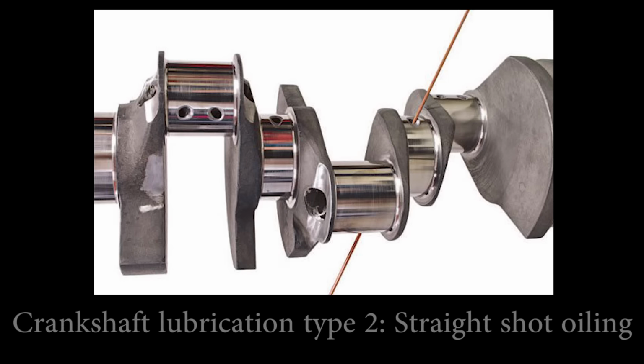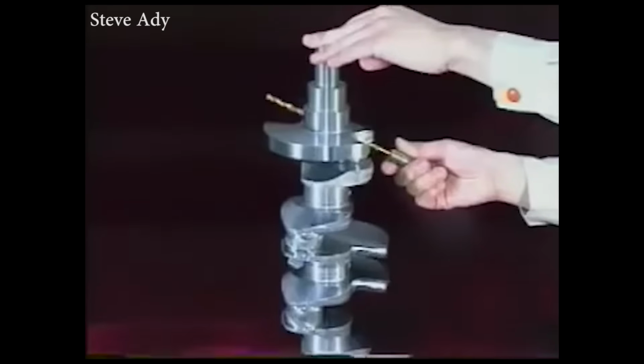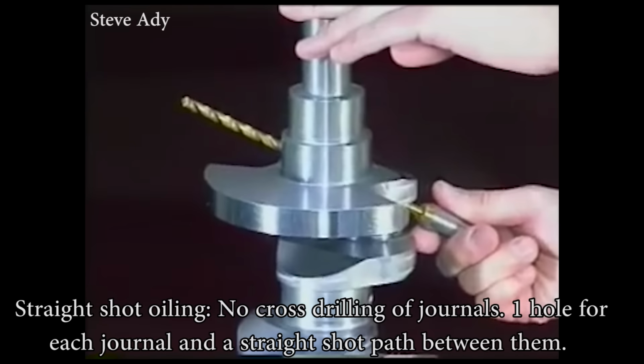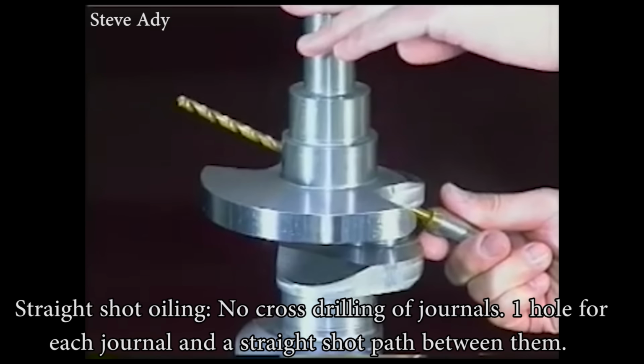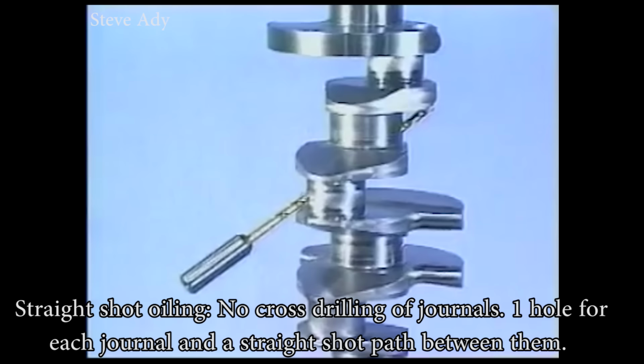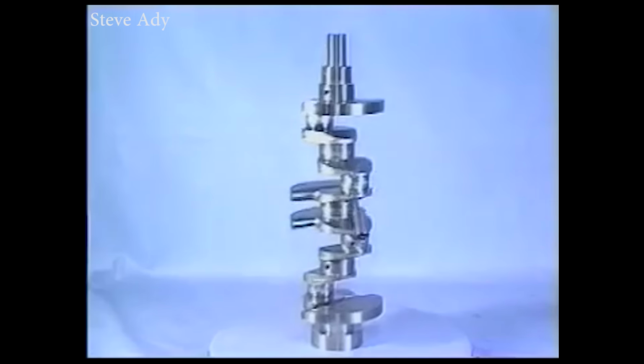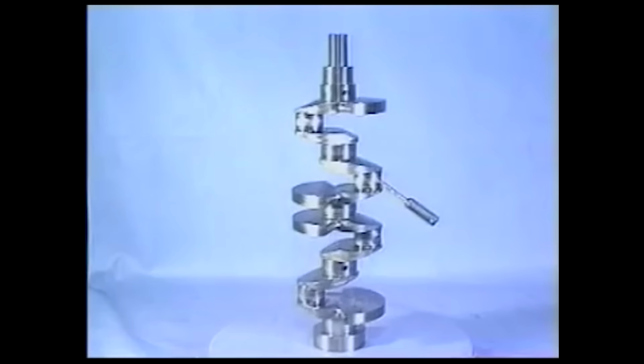An alternative to the cross-drilled design is a straight shot oiling design. When it comes to straight shot oiling, you won't find two holes on the main and rod journals of these cranks, but rather only one oil delivery hole per journal. And then you're going to see a straight, uninterrupted drilling between these two holes of the main and rod journals. And because of this, there's also no need to cap anything off.